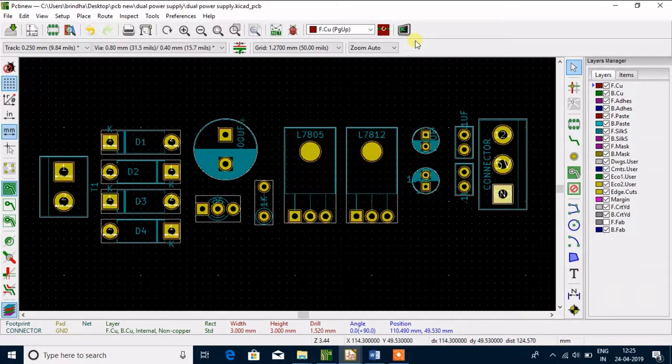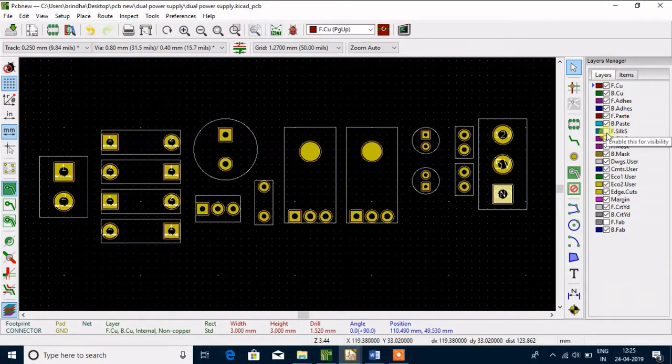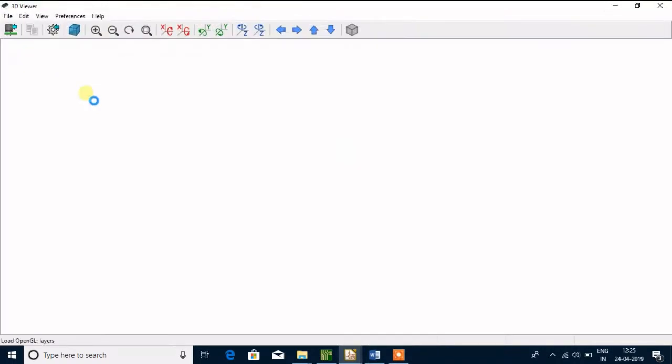Now you can notice that our diagram looks neat. So now just click silk layer, F silk. Now we can notice only the white side, and all the things that we have written have now disappeared. Why is that even so? Let us notice the 3D view after removing all the things.